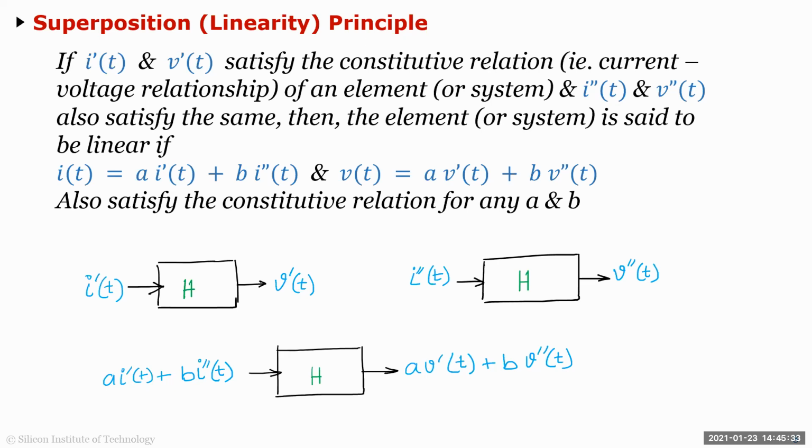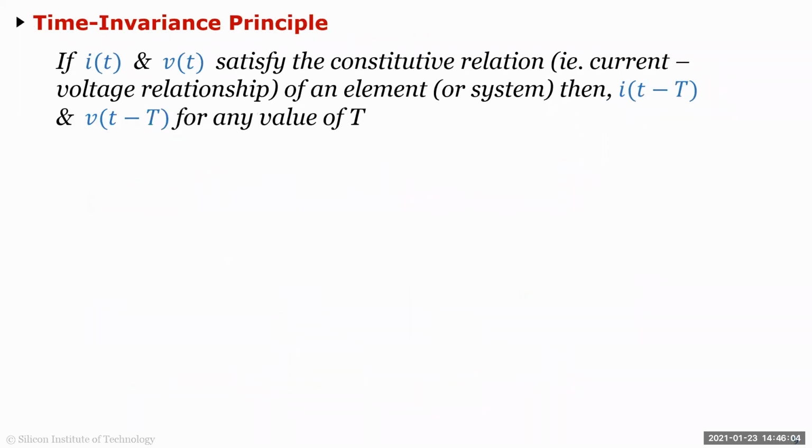So that's why you can take an RLC circuit and that's a linear system. But if you add a diode, then it's not, because if you apply superposition to a diode, it's not valid. So remember that if it's a linear system, you can apply superposition to find the output of two independent inputs by summing their two outputs, or taking the difference, whatever it is at the input. And it's reciprocal: if you want to find out if a system is linear or not, apply superposition as well.